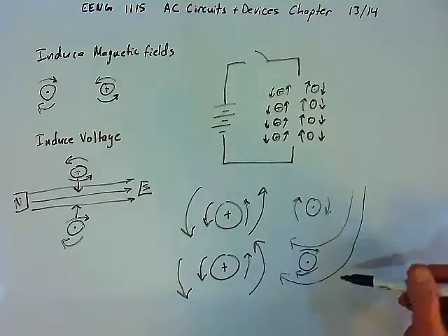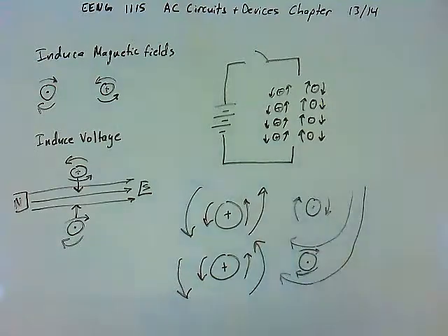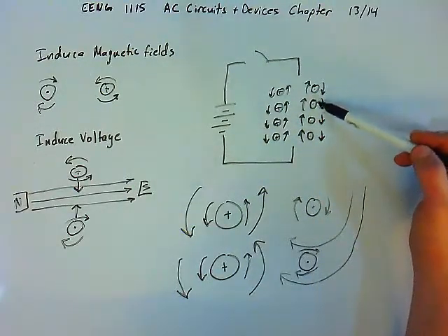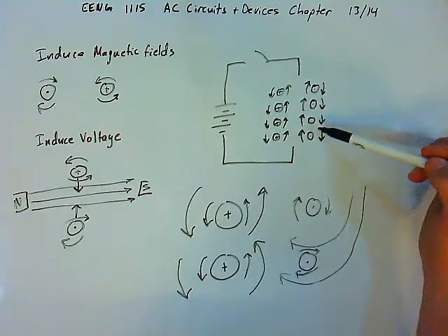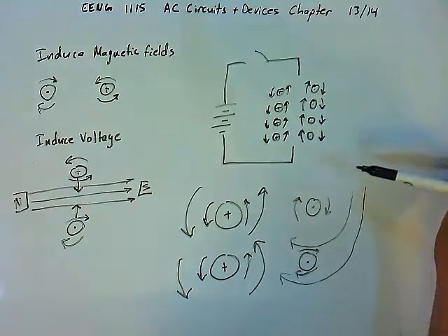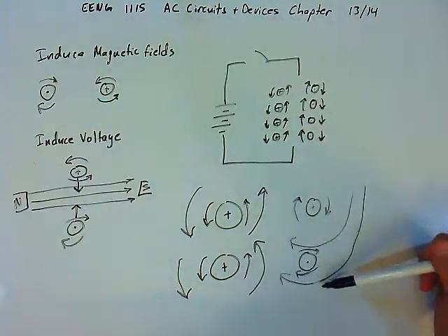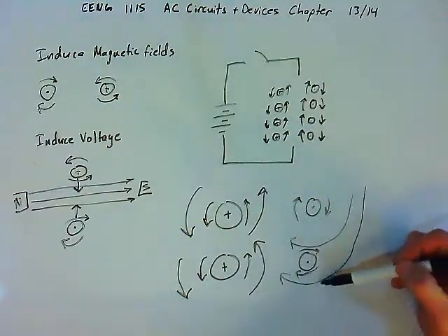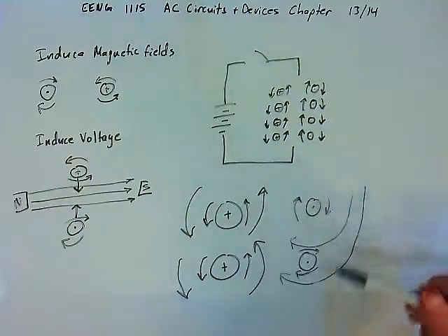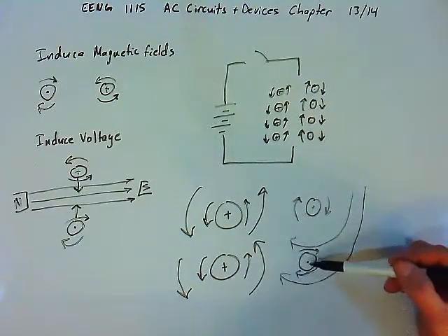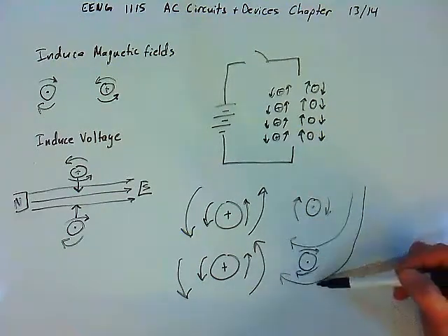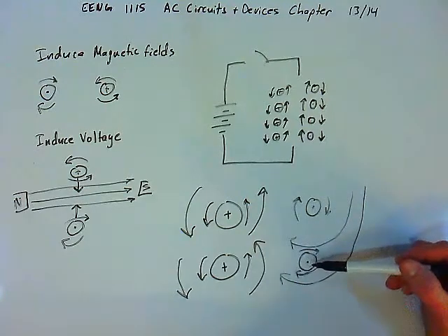And so this is a very interesting property of inductors. Remember that an inductor resists the change in current. So when the current started off as 0 and we closed the switch, the current wanted to increase, but the flux lines growing was slowing that change of current. The current could not change instantaneously. When we reopen the switch and the magnetic field lines collapse, the current in the inductor was already at some maximum value. When the flux lines are collapsing because the switch was opened, they're cutting the neighbors in such a way that the current, being at a maximum value, wants to remain at a maximum value. The collapsing magnetic field lines are trying to keep the current flowing in the inductor.